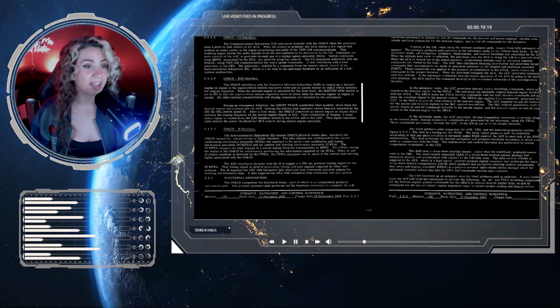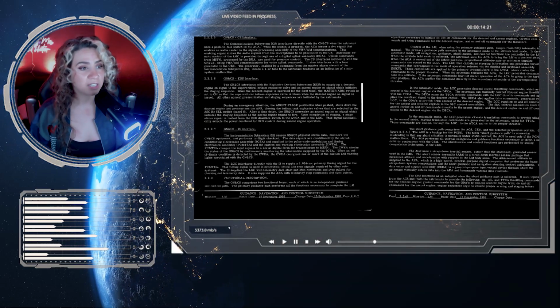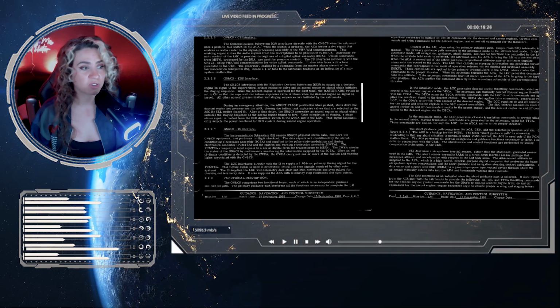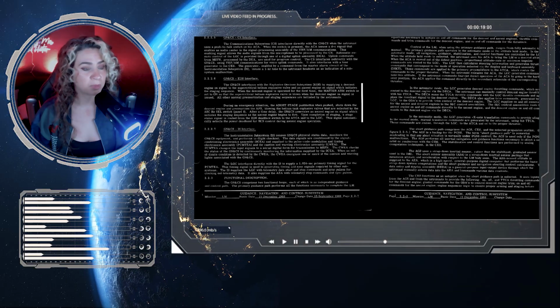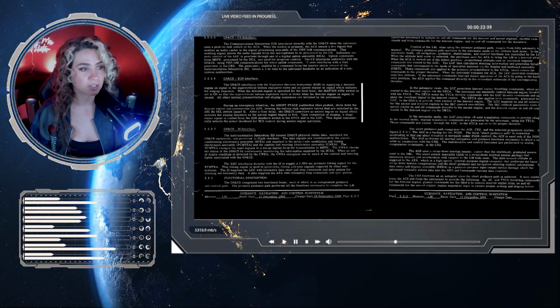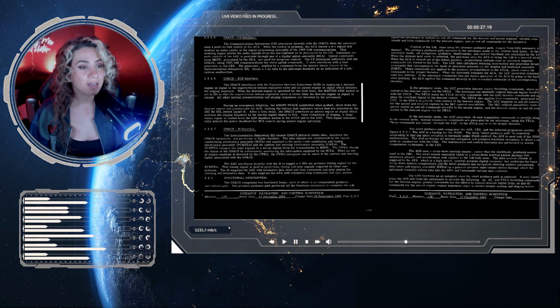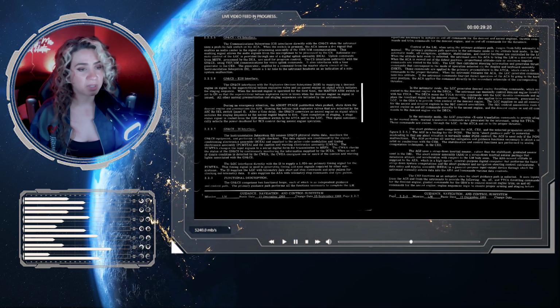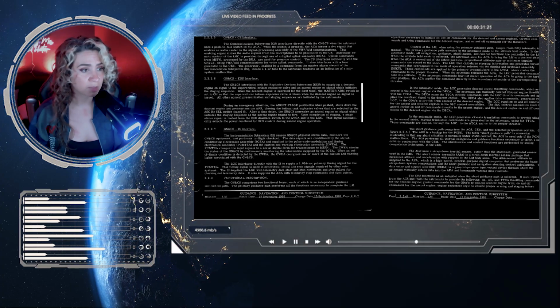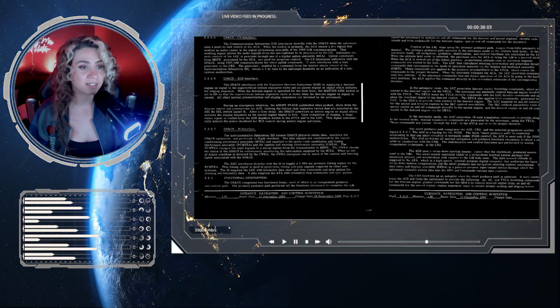The ASA sensed attitude is supplied to the AEA, which is a high-speed general-purpose digital computer that performs the basic strap-down system computations and the abort guidance and navigation steering control calculations. The data entry and display assembly, the DEDA, is a general-purpose input-output device through which the astronauts manually enter data into the AEA and command various data readouts.